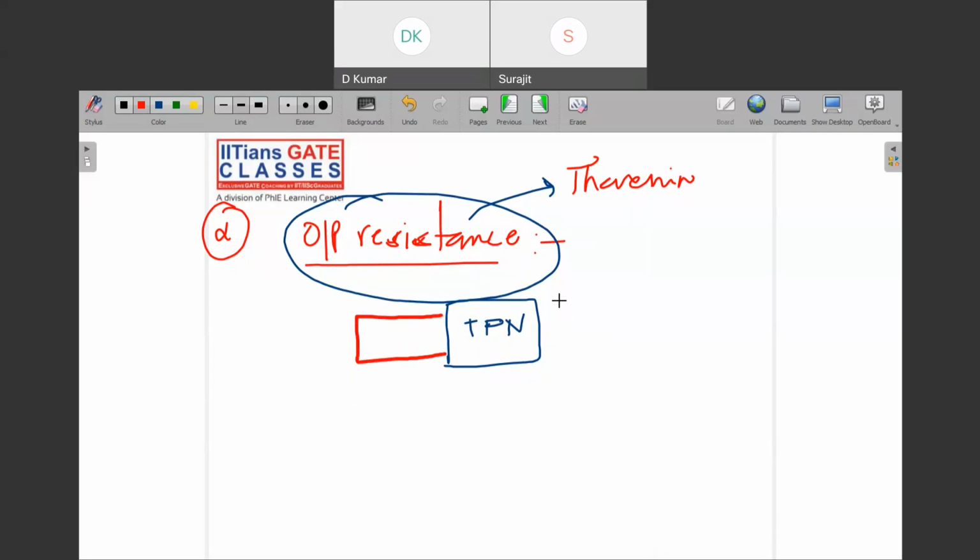And you have to apply some test signal here, right? Test voltage. You can apply some V test, okay? And then there will be a current flow, that is I test, right? And take the ratio of them. If you're looking back into the two-port network, the resistance which you will measure here is R out. Now you might be wondering why we are applying V test.